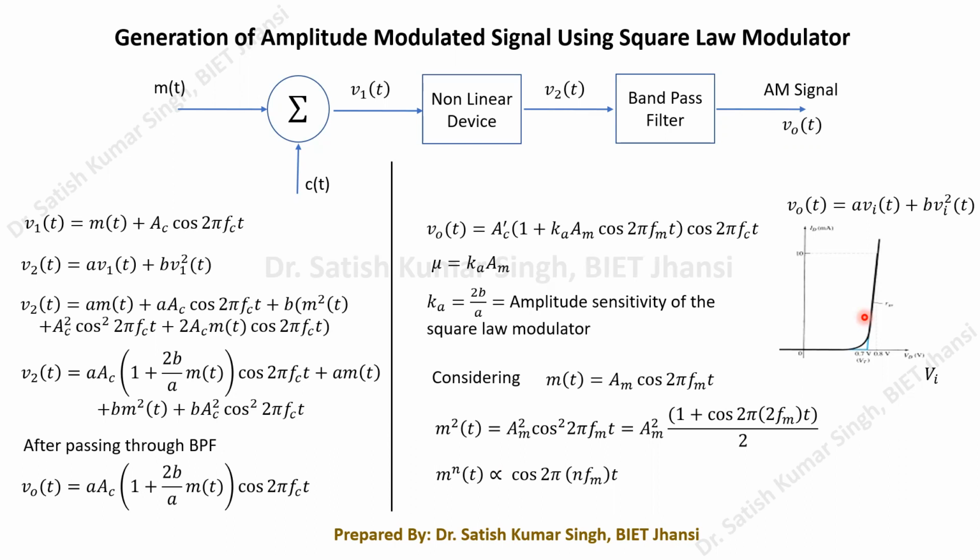Generally, for approximation purposes, we neglect the minus 1 term. So we can understand that this VI characteristic of the diode follows the exponential law; it is an exponential curve. In a certain range of this exponential curve, we can write the exponential series. As we know, e to the x can be written as 1 plus x plus x squared by 2 factorial, plus x cubed by 3 factorial, and so on.